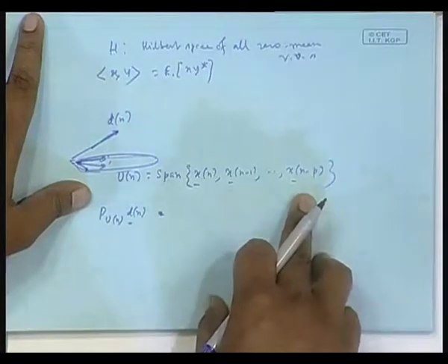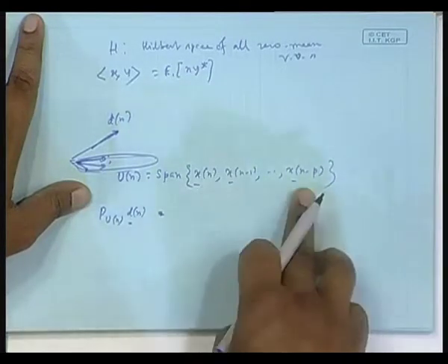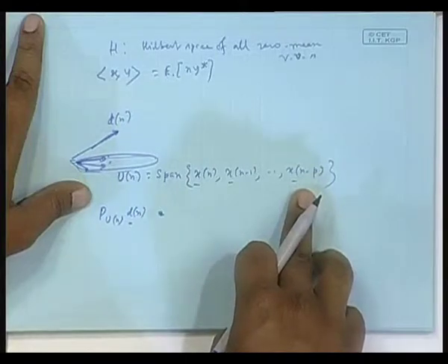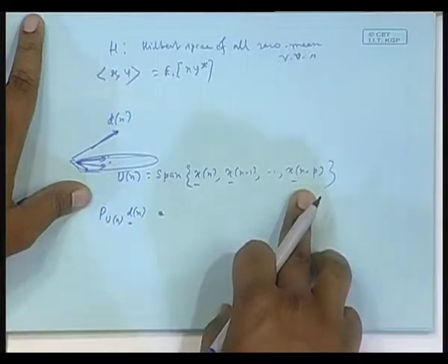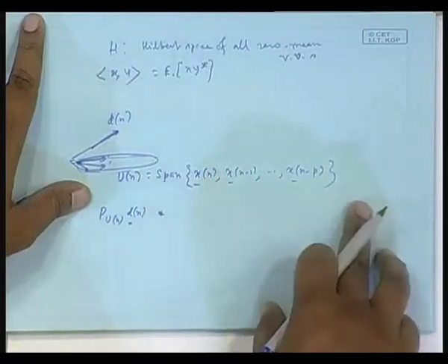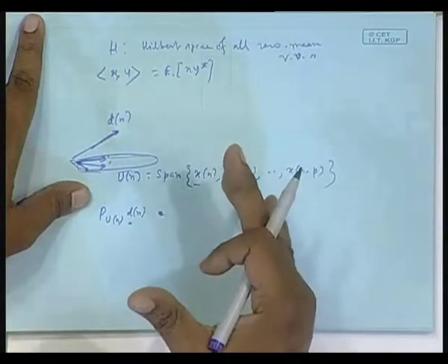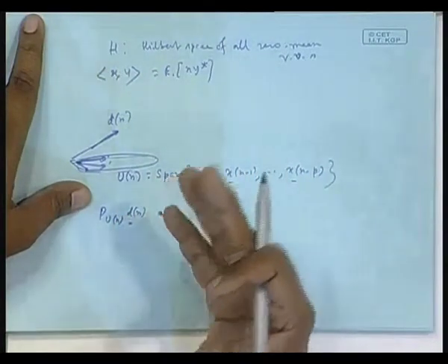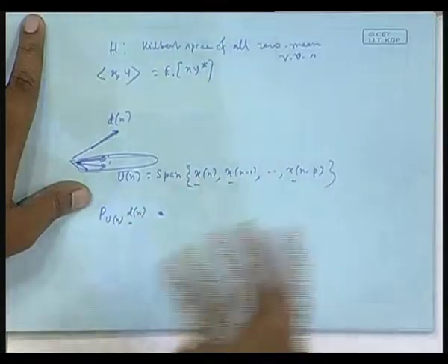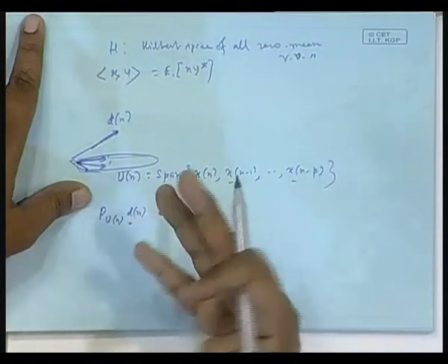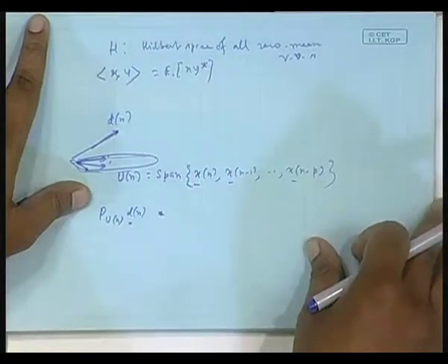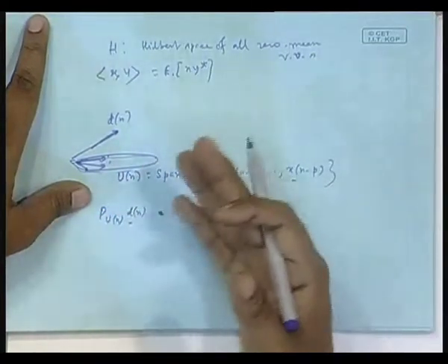But they are not orthogonal. The lattice filter orthogonalizes a set in a Gram-Schmidt manner. That we will see. The lattice filter will generate an orthogonal set out of this sequence, that is, an uncorrelated sequence. You can also say it generates a white sequence. You can take a correlated sequence and generate a white sequence out of it. Uncorrelated means white. All those things, I am just dropping hints.